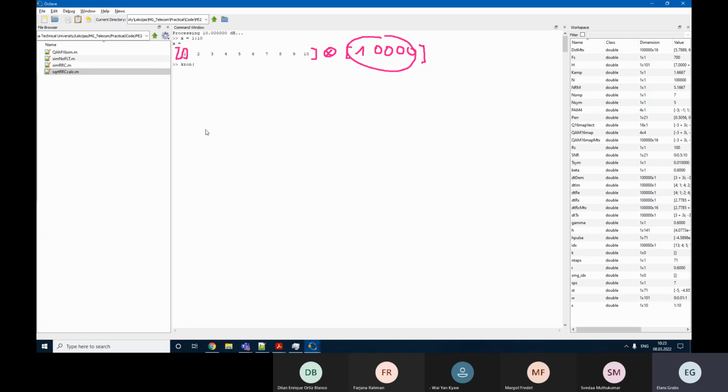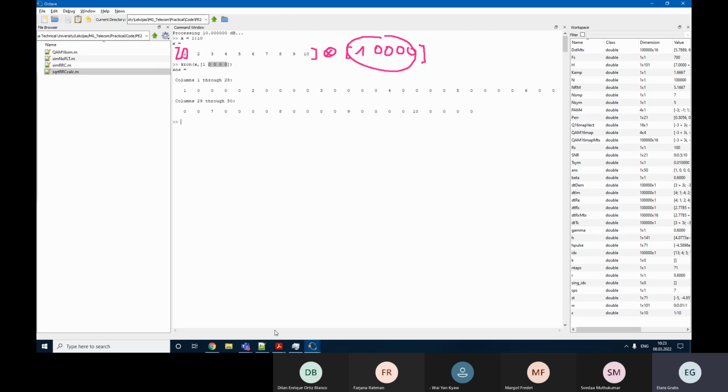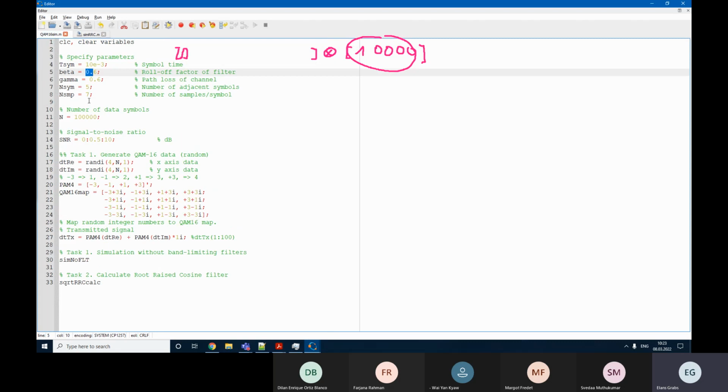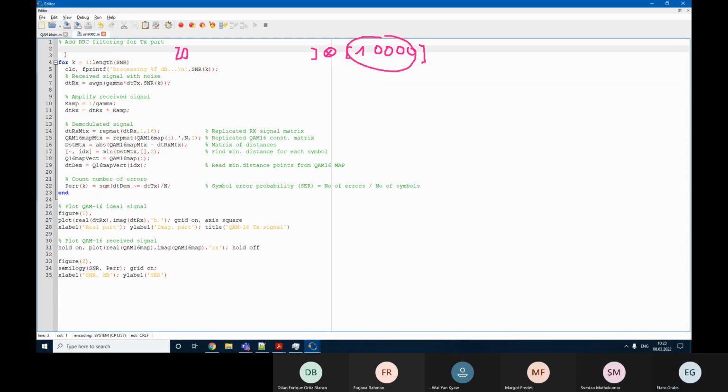The first variable is our original data array or vector. The second is the mask that we want to apply. As a result of this Kronecker multiplication, we have exactly what we need. In our particular case, we need to add as many zeros as specified by your samples per symbol parameter, except for one, because of these 7 samples, one of them is actually a symbol, and the other 6 are zeros. So this procedure is called data interpolation with zeros.